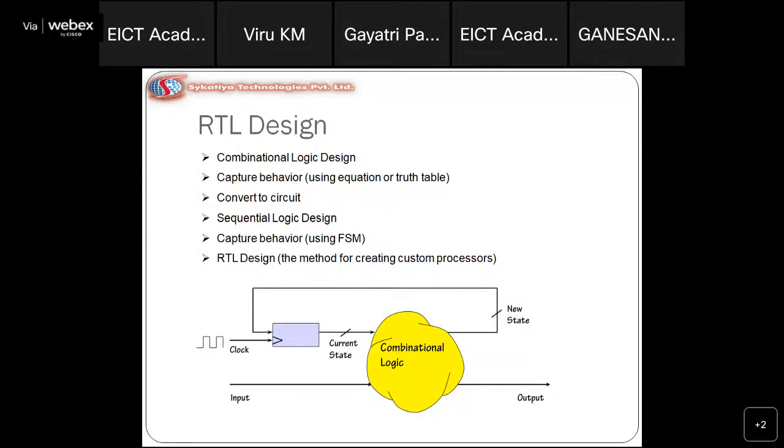For designing, checking your designs, checking your synthesis and timing, you can do it with any tool. But for downloading to the FPGAs, you have to use the specific tool for the board and the specific programming cable. If you're using Xilinx, you have to use JTAG, Joint Test Action Group. That cable comes with a 20-pin cable connector. Nowadays all FPGAs come with a USB port also, and you can use that. But mainly Xilinx ISE or Vivado tools use the JTAG connector.